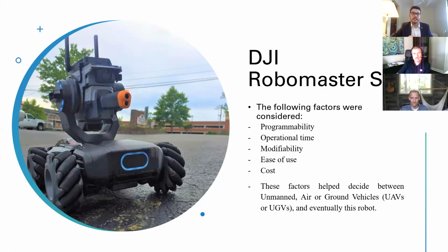Let me talk about UAVs for a second. A lot of the UAVs that are programmable at this point in time, especially educational UAVs, are not only small in size, but their flight times are also limited to about 7 to 13 minutes. A lot of the non-programmable UAVs are actually more advanced. They're used for video capturing or the drones we generally use in construction. They're of good quality, pretty sturdy, and their flight times are, say, 20, 30 minutes. That is kind of what we needed, but they were not programmable.